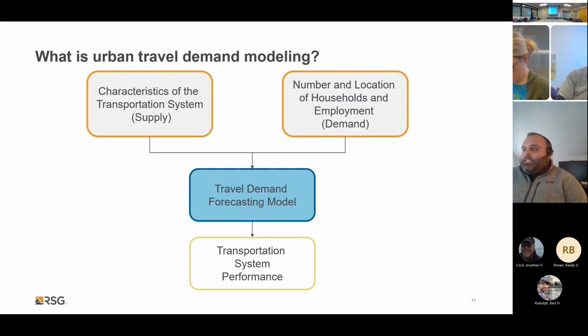And modeling can estimate, based on assumptions about transportation system users in the future, how changes in size and character of the population will impact the transportation system. As more women have entered the workforce throughout the years, for example, the increase in the number of work trips per household has placed a greater peak hour demand on transit and highway facilities. And we can measure these types of changes in household characteristics and household trip making characteristics through the model.